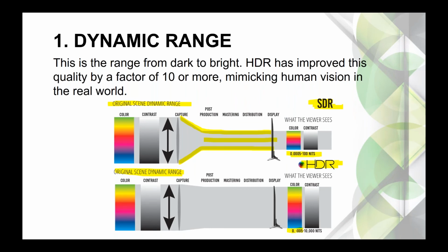The metadata and the headers, the information going through the distribution systems, spell out high dynamic range and wide color gamut. Now, you're probably thinking, well, I haven't seen a 10,000 nit display. You're correct about that. But we are exceeding 1,000 nits, up to around 1,500 nits, in the latest and greatest LCD technologies with LED backlights. And we're seeing about 600 to 700 nits with your OLEDs.